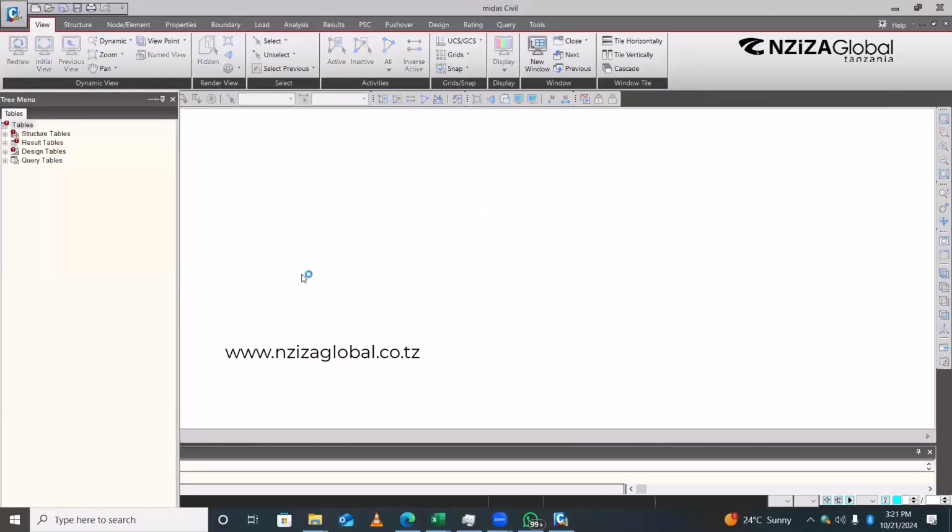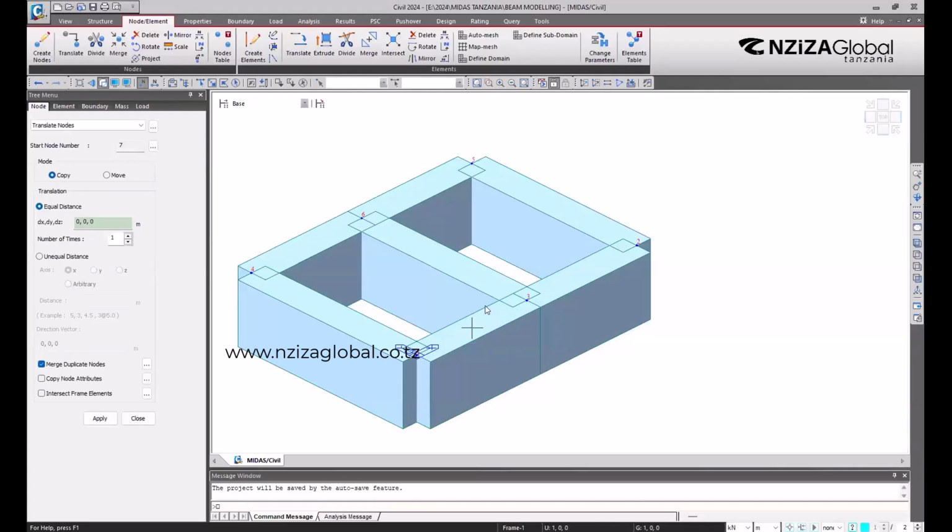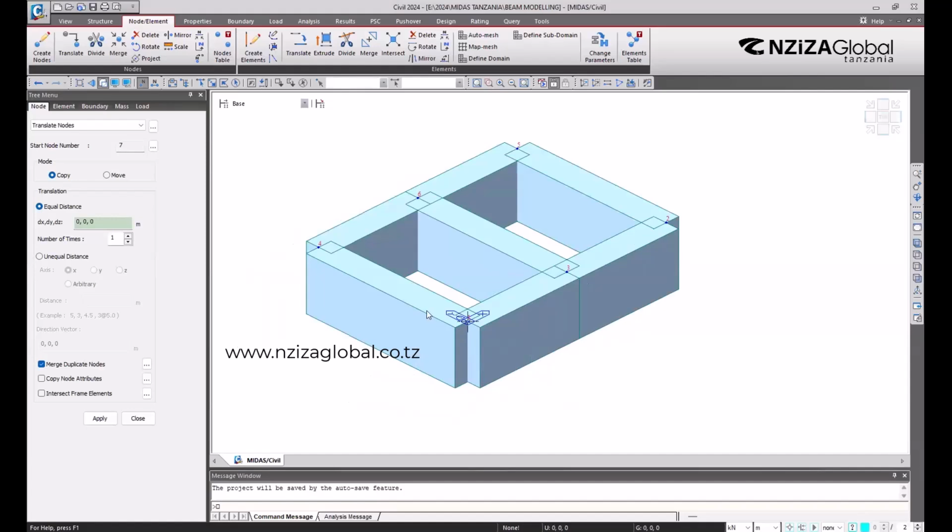I'm going to share again. You see? So I was telling you, I want to extend this box downwards. We had 1 meter, maybe I want to make it 2 meters. Before we had this section. This is the one we created. Now we created the side walls in the Y direction. Now I want to increase the depth of these side walls from 1 meter to 2 meters going downward. So to do that, I'm going to use extrude.